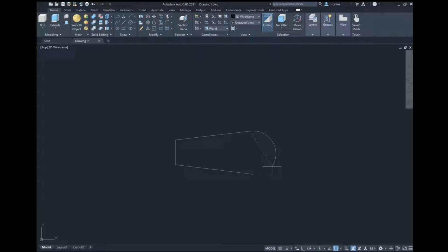And what I do is I have my O-snap on. I would just snap on the first point there like that, click, and I'm done. I can go on and on, but I'm just going to end there and just press escape. And there I have my polyline, which consists of lines and arc.